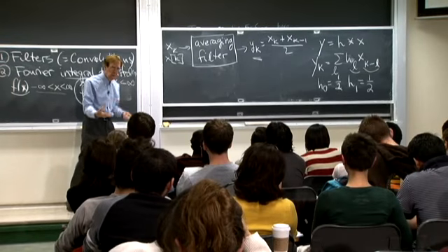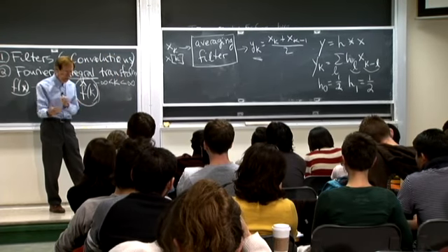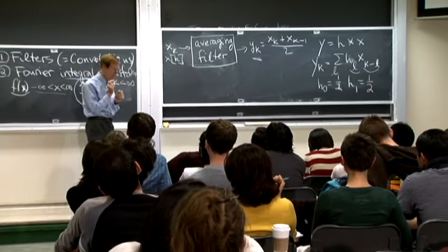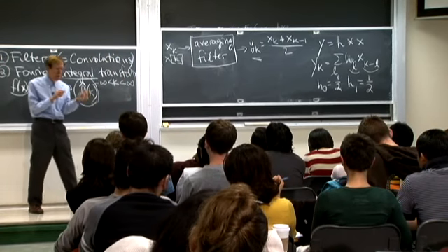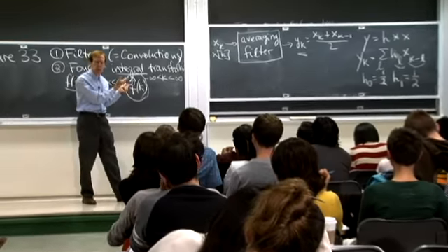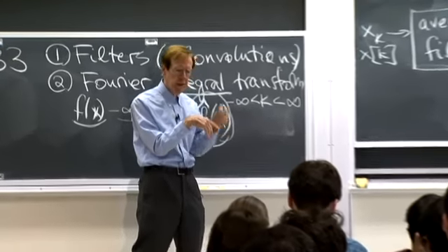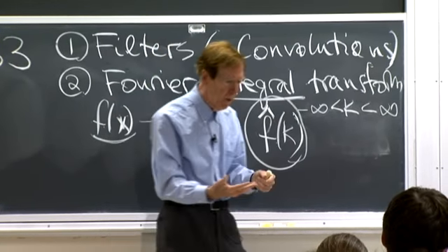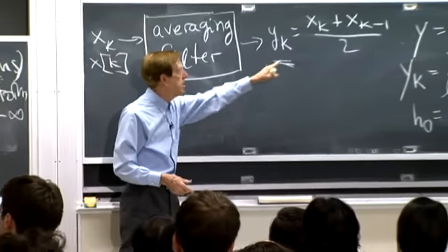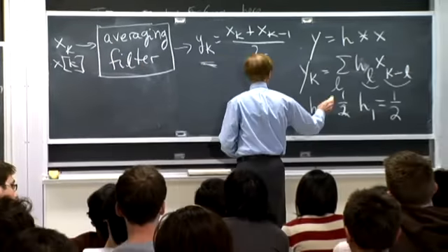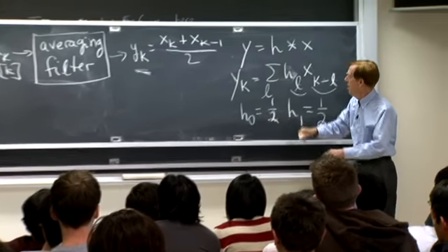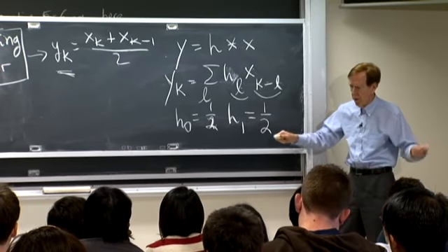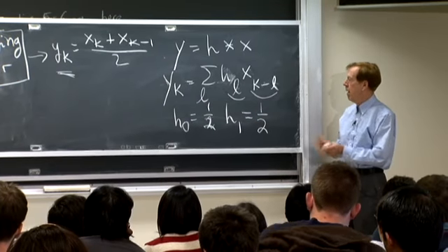But you want to keep the signal. So it's always this signal to noise ratio. That's the SNR, PSNR. It's a constant expression, signal to noise ratio. And we're sort of expecting here that the signal to noise ratio is pretty good, high, mostly signal, but there's some noise. This is a very simple, extremely short filter. So this vector h is a proper convolution. You could say h has infinitely many components, but they're all 0 except for those two. Right, do you see it?